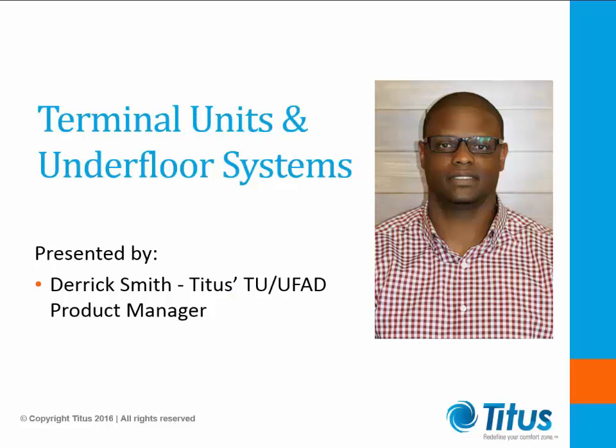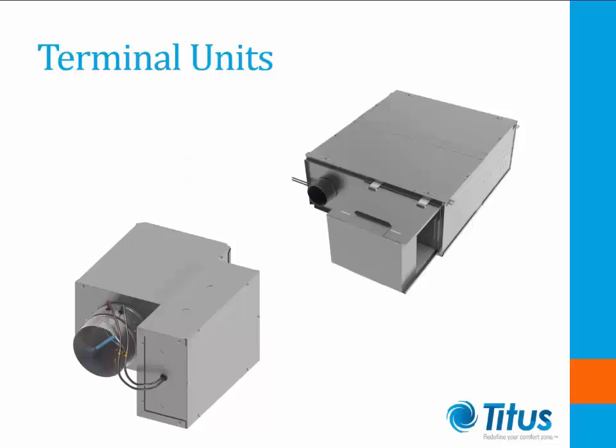When it comes to zoning, you first have to understand the type of system that you're using. The system in particular that we focus on here at Titus is a central plant air conditioning system. When dealing with a central plant air conditioning system, you are delivering a certain amount of air to a particular building. But how do you go about breaking down that air into zones in order to ensure thermal comfort for the occupants? One way of achieving this is by using terminal units.